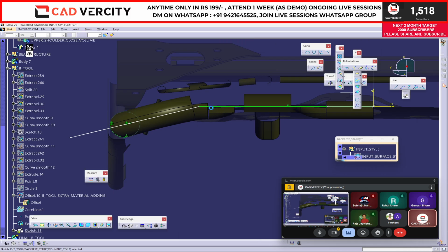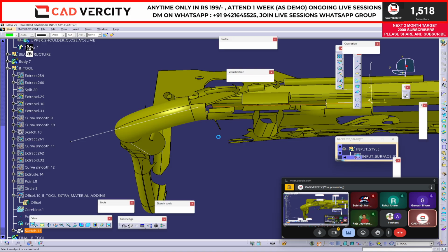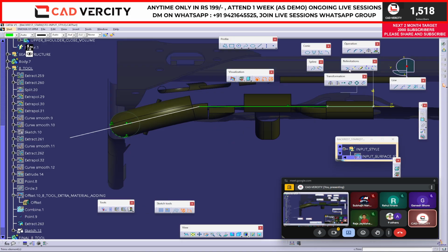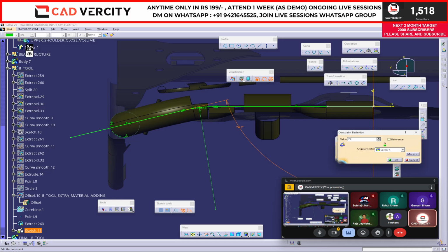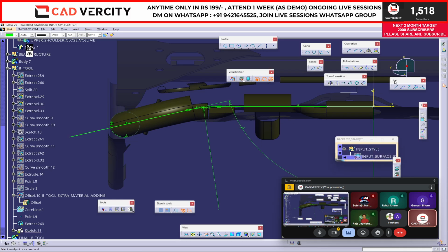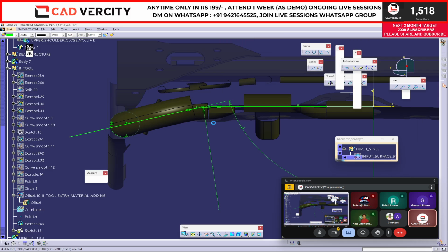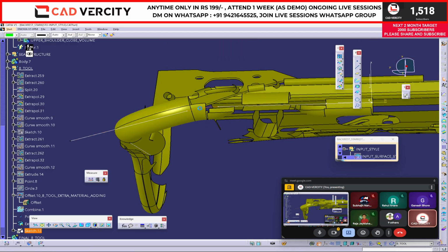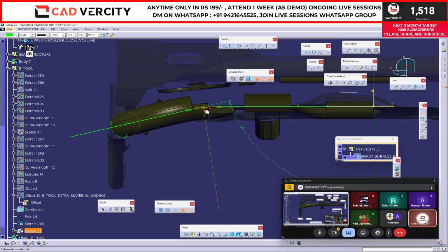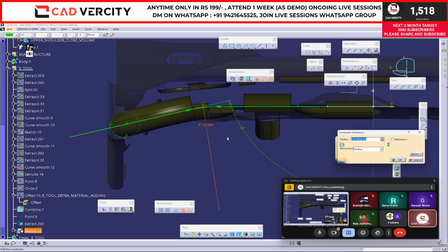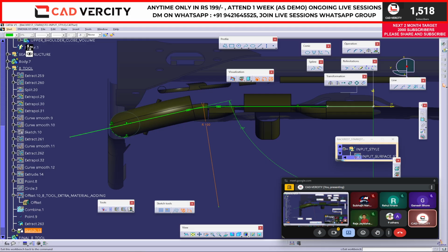Exit, or instead of this, double click. Let's apply a corner, left side, and lock the angle tentatively. Okay, we don't know the angle, just lock the angle. Let's make it 74. Let's make it 75. Perfect. Fillet also. What is the value? 100, 102, make it 100. For now, we will check later.